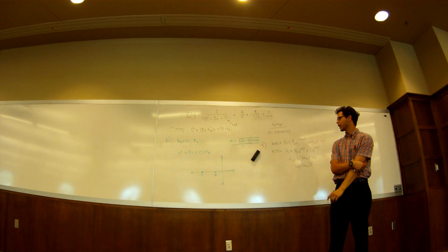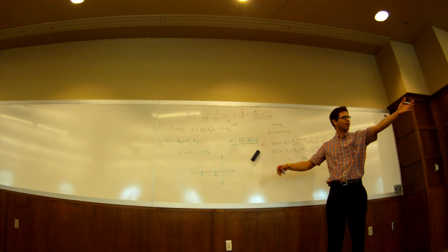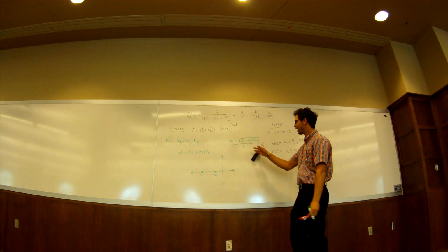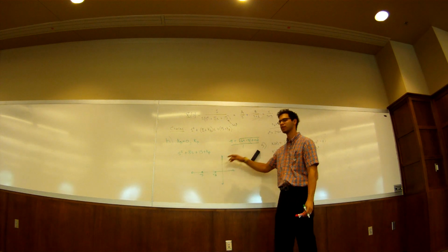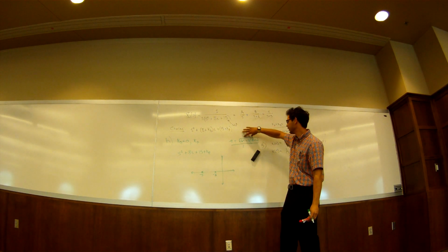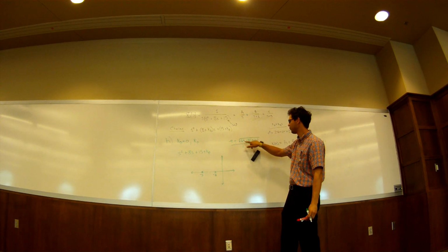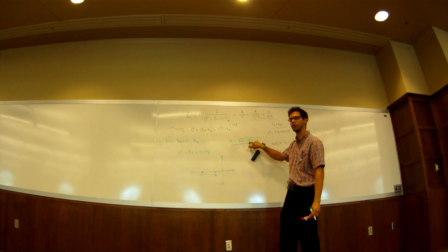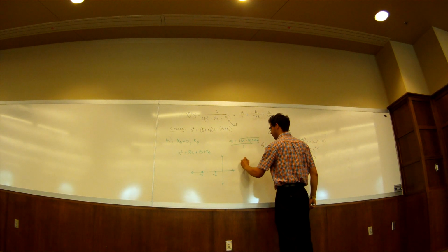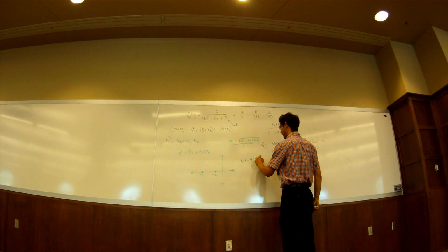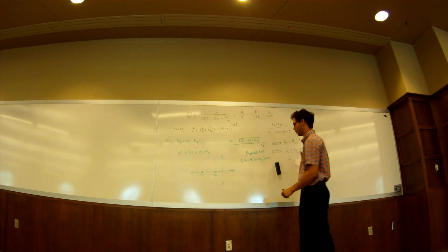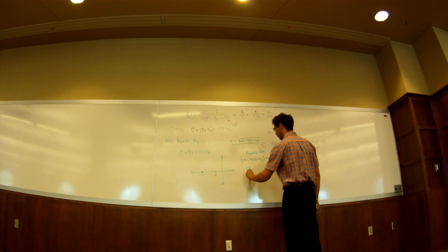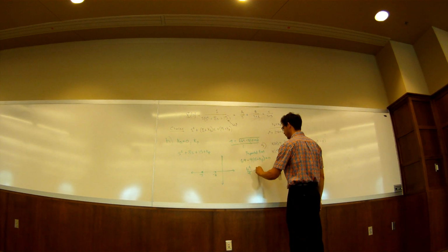Yeah, the algebra, right? Okay, so with this, now we can try some of these fancy things that you're talking about, right? So how do I make this guy go here? What do I have to do to this thing to get my 2 repeated roots? Set the square root to 0. Make the square root 0, right? So I need 4 times 15 plus Kp to equal 64. Let's just do this a long way. I need 64 minus 4 times 15 plus Kp to be 0, and this will give me a repeated root. So I get 64 over 4 equals 15 plus Kp.